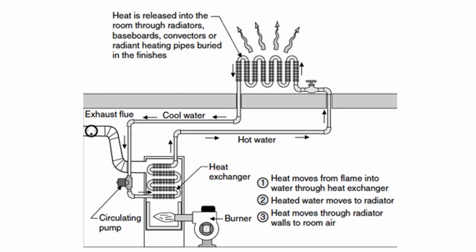Generally speaking, a boiler is going to cause a significant amount of heat to be produced in a burn chamber, which will then transfer through combustion gases heat to a tube which has water inside it. The water is then heated to a predetermined level and then either circulated or just gravity fed through a pipe to something called a heat exchanger or radiator, which then transfers the heat from the liquid to the air or another surface.